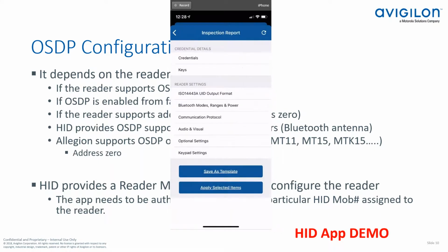And then a couple other things in here. And this one is pretty interesting. Let's say that you have a credential that is not fully compatible, or, in this case, this is an HID reader and I'm using a credential that is not HID. I'm not going to be able to open the encrypted box inside of that credential. So I'm dealing with a smart credential, and I'm just going to read the external serial number, the CSN.